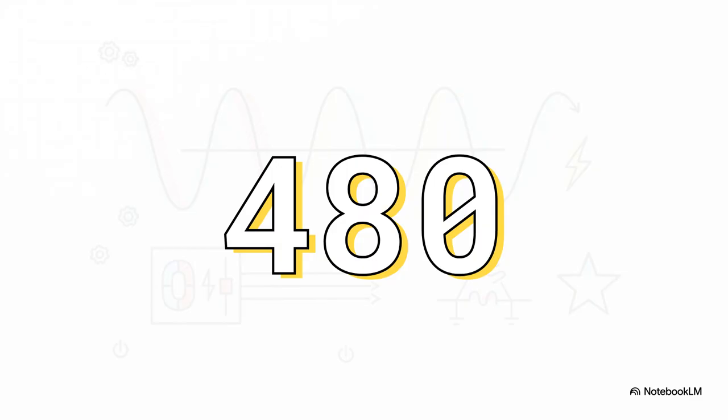That 120-degree shift also defines our voltages. In a balanced three-phase system, the line-to-line voltage, which is just the voltage measured between any two distinct phases, equals the square root of 3 times the phase-to-neutral voltage. This is an absolutely vital mathematical constant for electrical engineers. It's exactly where your familiar industrial voltage pairs come from. For example, if your phase-to-neutral voltage is 277 volts, multiplying that by the square root of 3 gives you a line-to-line voltage of 480 volts.